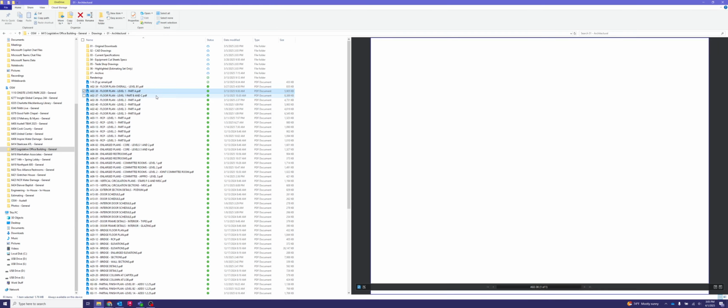So, yep, just like we talked about, looks like there's going to be a finished end on the left-hand side of our elevation here, because these cabinets are going to be seen. They are open to the room here. On the right-hand side, there's actually a wall right here, and they did draw in a filler, which is great because we will definitely need one. They're showing it at 1 inch, which again, we usually draw them at 3/4, but we can draw them at 1 inch just to appease them if we need to.